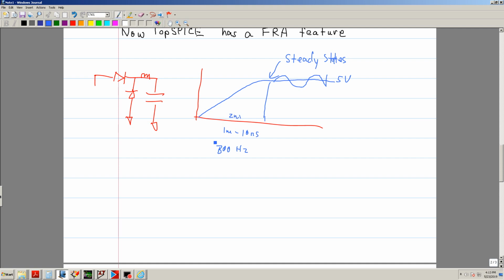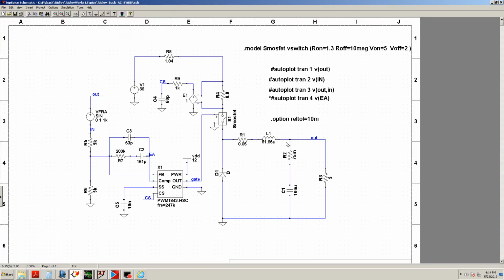Okay, so to simplify this, what you can do is a pre-run. You let it run and you see what is the voltage that this capacitor will eventually reach. In this case it's 5 volts, so you set this to 5 volts. And then you also set the voltage that this capacitor will reach. So you initialize them, and that will speed up your simulation.